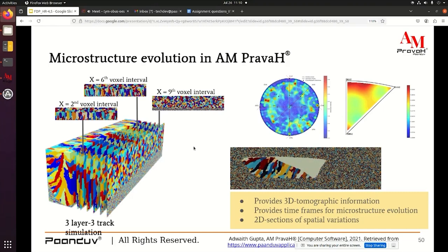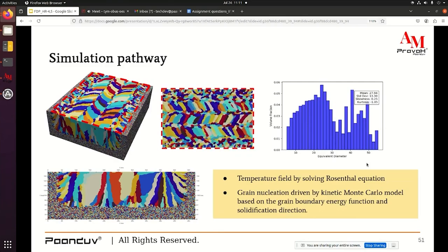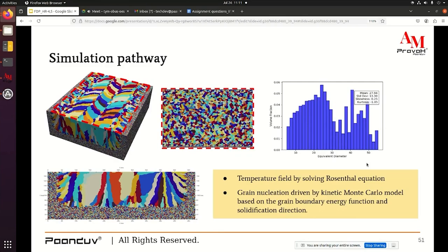Extending to that, we have crystallographic data that we have plotted based on the different misorientation angles. Other than that, we have 3D tomographic information that we can use based on our ease. To get the perfect melt pool geometry, we considered the data directly imported from the thermal field data, directly imported from the CFD. So these are some of the trivial informations that we can capture.